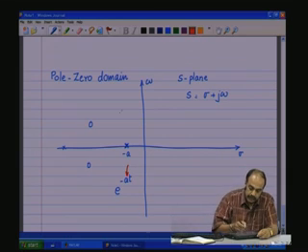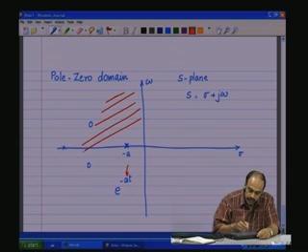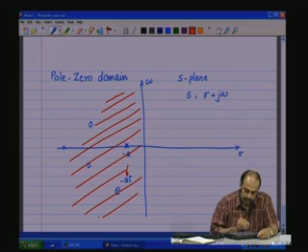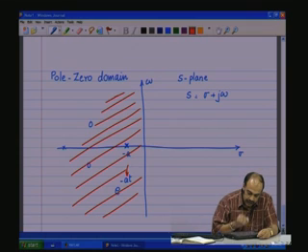Of course, it should be noted that in a physical system all the poles and zeros will exist only on the left half of the S plane, because only in the left of the S plane any pole or a zero would have e to the power of minus a t, which decays.